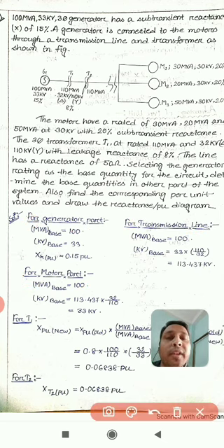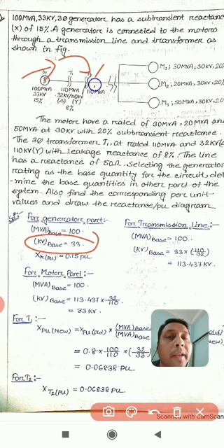For the base voltage, first we start from the generator side. As we have considered the generator base itself as the system base, whatever is written on the generator remains the same. So the generator base is 33 kV, and my system base is also 33 kV. The base for this portion is 33 kV. Now you start with the generator and think that you have thrown 33 kV from this side, and according to the transformer ratio it will automatically change on the other side. Again there is a transformer, so it changes on this side. There will be continuous change of the base voltages. Whenever you cross a transformer, the base voltage is supposed to change, if the ratio is not 1:1.